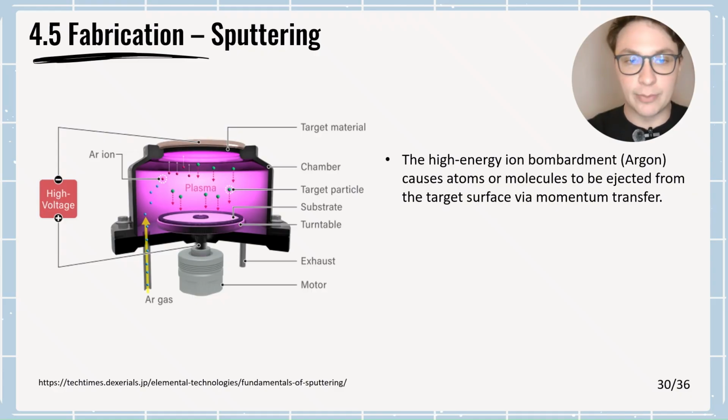Basically, the bombardment of this argon ion on the target material causes the atoms or the molecules, it depends on the material of the target, to be ejected from the surface of the target, and to be transferred to the substrate on top of which we would like to deposit our material.